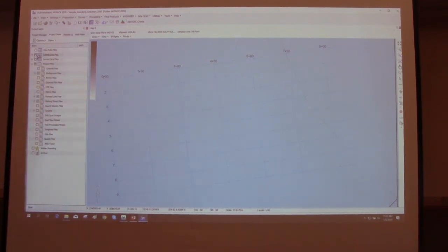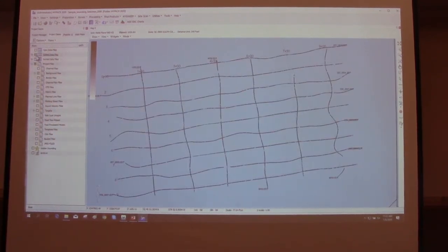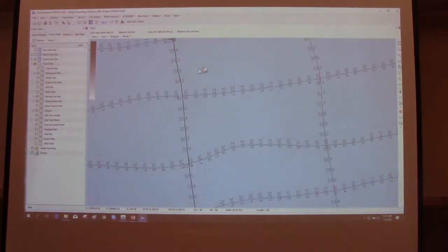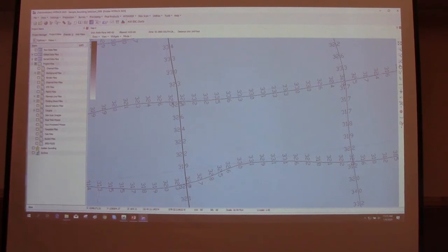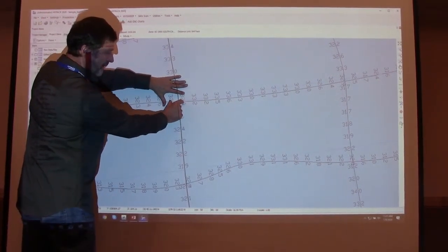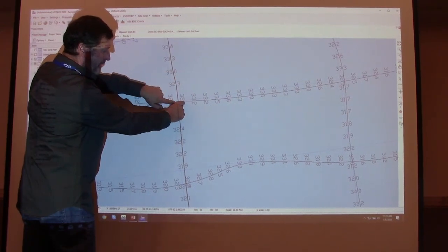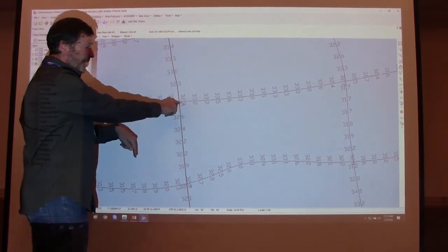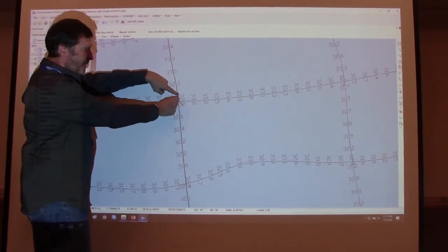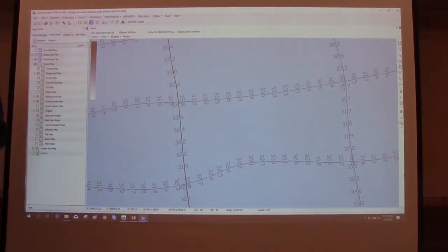Zoom in. So if I had a 50-foot radius here, it's looking for the two closest soundings on each side of the intersection. It basically draws a line and interpolates, gets a depth right at the intersection, and it does the same on the opposite ends here. And then it finds the difference of those.